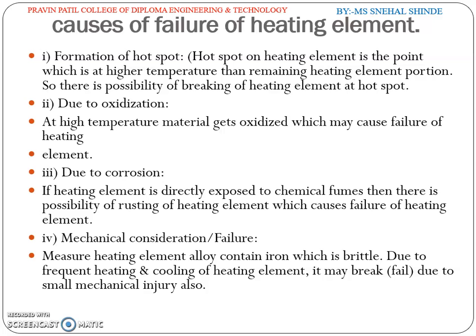Second is due to oxidization. At high temperature, the material gets oxidized, which may cause failure of the heating element. Third is due to corrosion. If the heating element is directly exposed to chemical fumes, then there is a possibility of rusting of the heating element, which causes failure of the heating element.